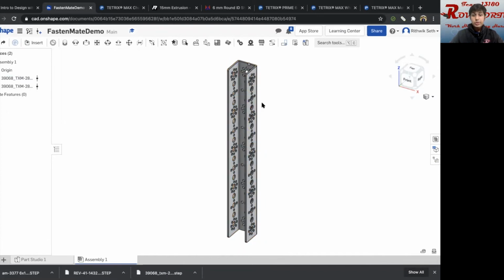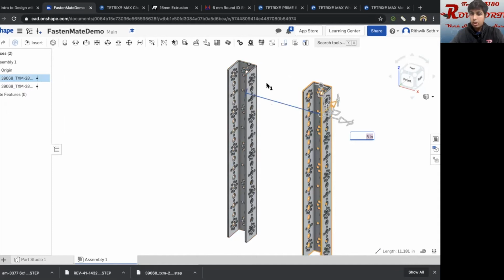The first step we're going to do is click on the cube, or the channel. After we click on the channel, you'll be greeted with these arrows. These arrows will help you move in a specific amount. So let's move this. You'll be greeted with a text box that says 0 inches. We're going to type in 5 inches. Then our channel will have moved, and we'll see that there's actually 2 channels just completely overlapping.